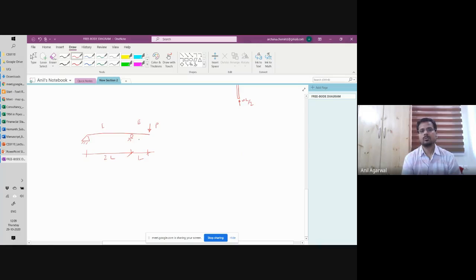That's okay. We want to know the bending moment diagram of this problem. Why do we want to know the bending moment diagram? Because we are assuming that deflections are caused only from bending moments. Saying that shear force and axial forces do not cause any deformation is a wrong way of saying it. It's basically that we are ignoring the other types of deformations.